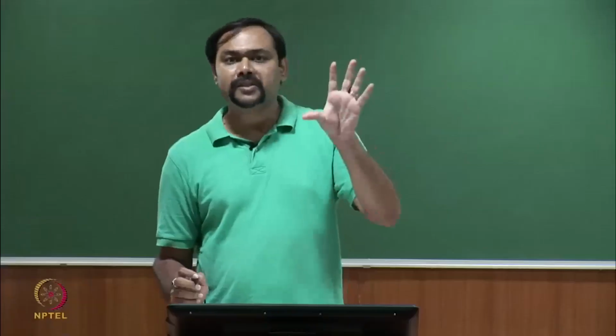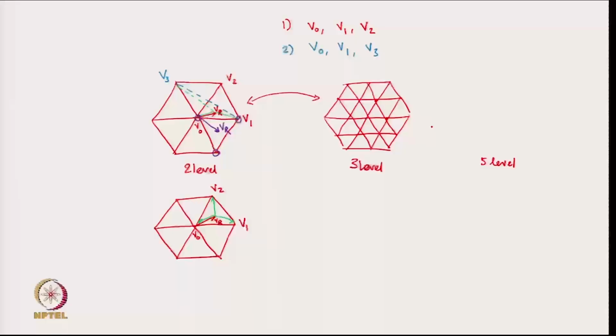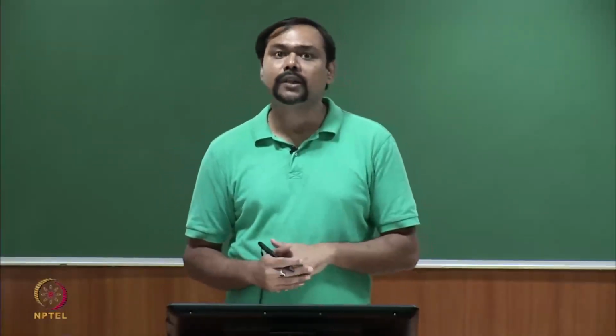So, we will have a lot of space vectors, and what will happen there is the instantaneous error. Suppose you are switching this Vr; of course, we will use this one and this one, these 3 nearest enclosing vectors. The instantaneous error is smaller. As the instantaneous error is smaller, it indicates that the harmonic performance of the 3-level converter will be superior as compared to the 2-level converter.